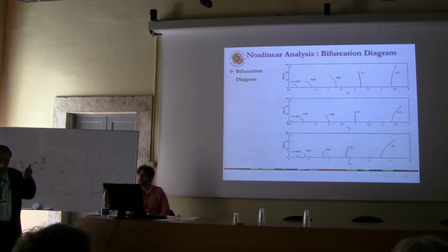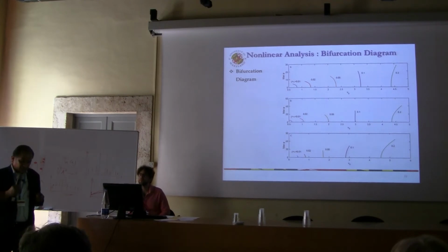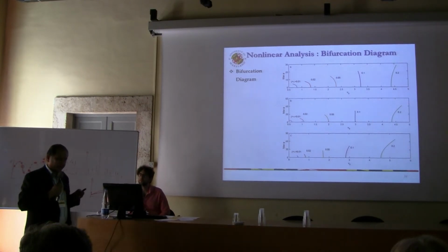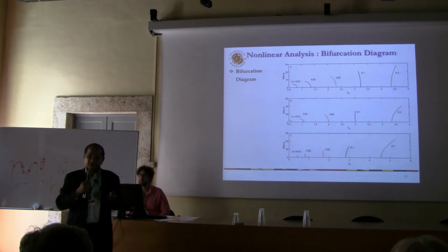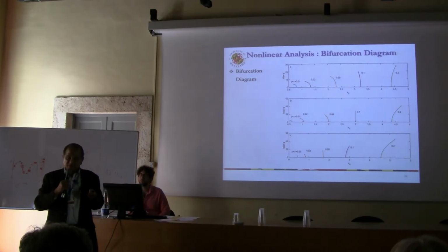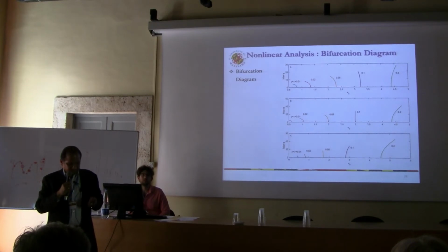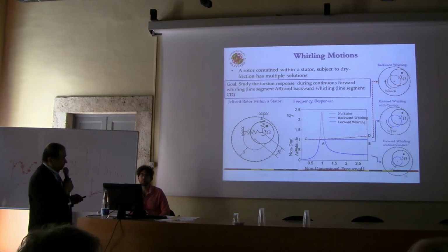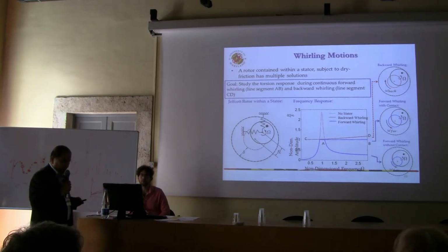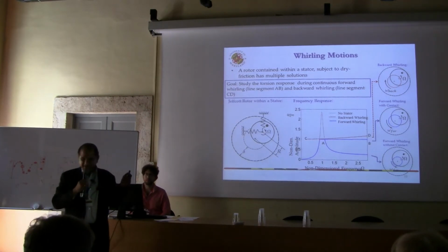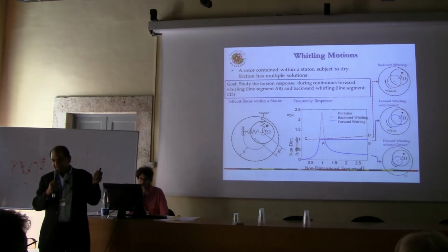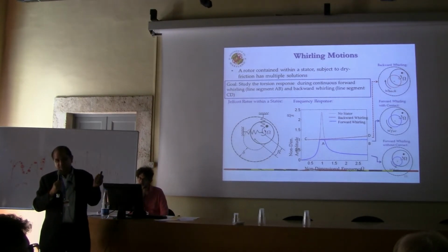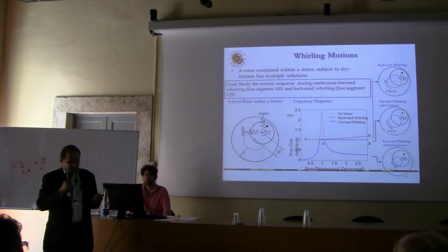So that concludes one part of the talk, in which the whole goal was to look at stick-slip dynamics, how to predict those, and what features one needs to take into account to capture them. Instead of stick-slip, the next part I'll segue into is whirl dynamics. Whirling motions are another instability that happens in these strings. Here I'm isolating the system and looking at a case where there's no cutting action. I'm purely looking at whirl dynamics.